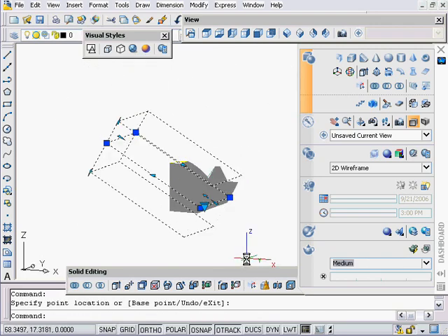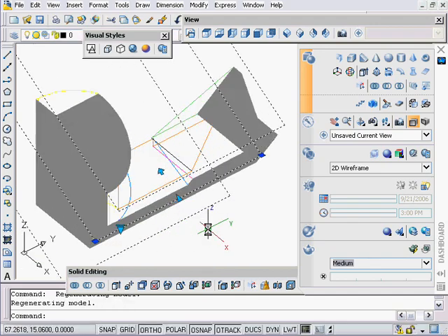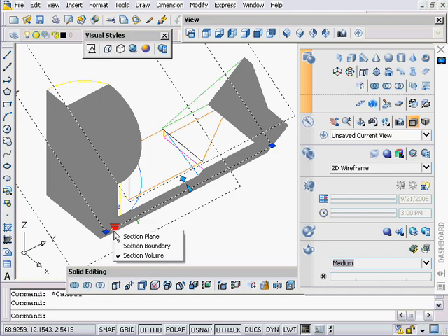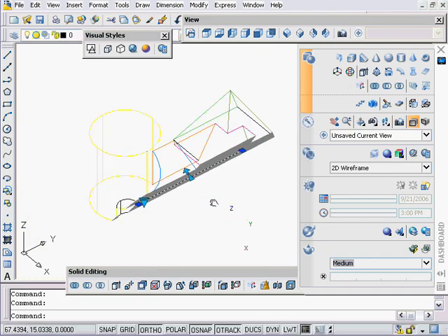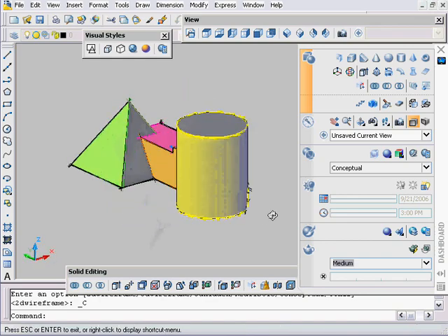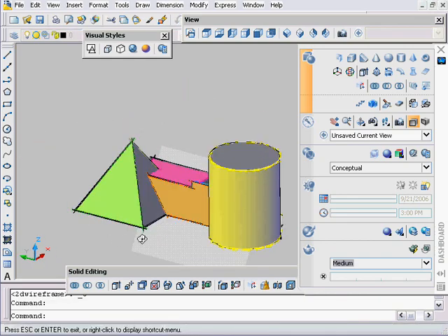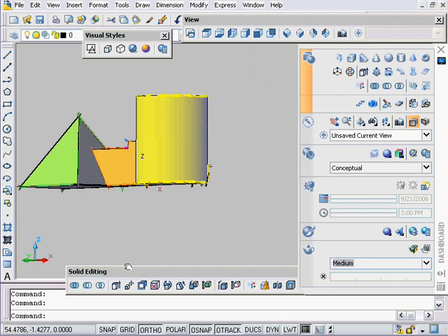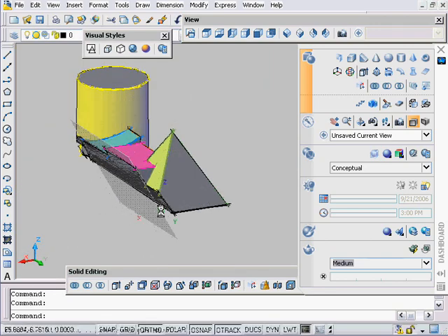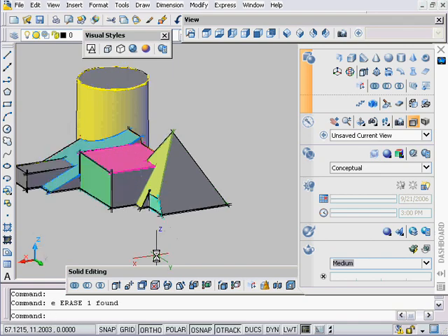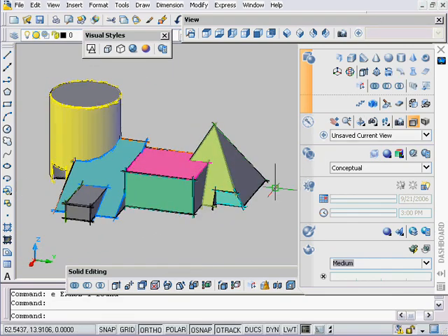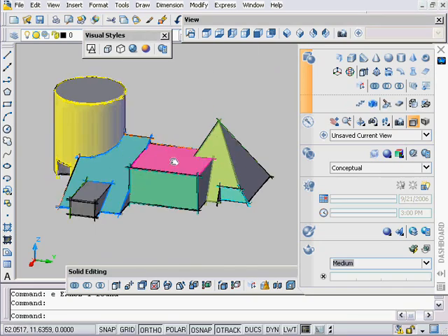3D aspect where you can squeeze it down this way as well. Just insane how many settings we have on here. And back to section plane. Okay. My conceptual view. Spin that around with my objects where I just used my colored faces. Shift middle mouse. And then again, the nice thing is you erase it and everything comes back just the way you had it.